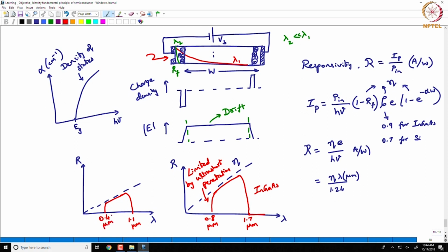Now you have something called UV enhanced silicon photodiodes in the market, and they extend the absorption to even like 0.2 microns. And what they exactly do is you would have a much smaller structure to start with, right? It's a much thinner structure to start with.